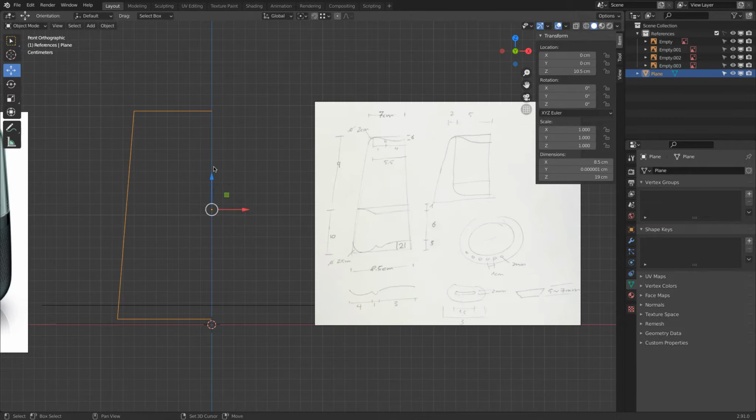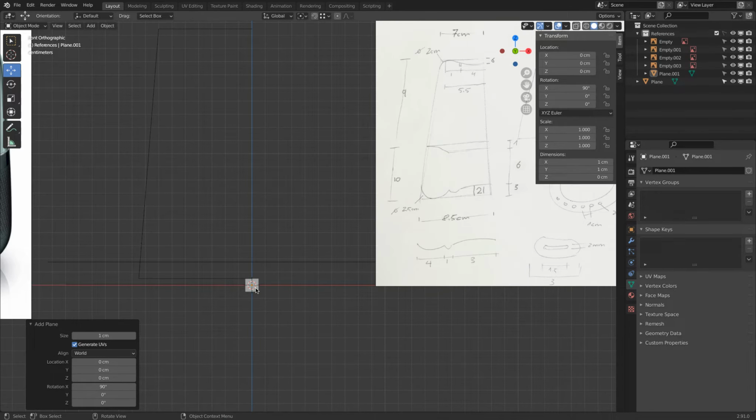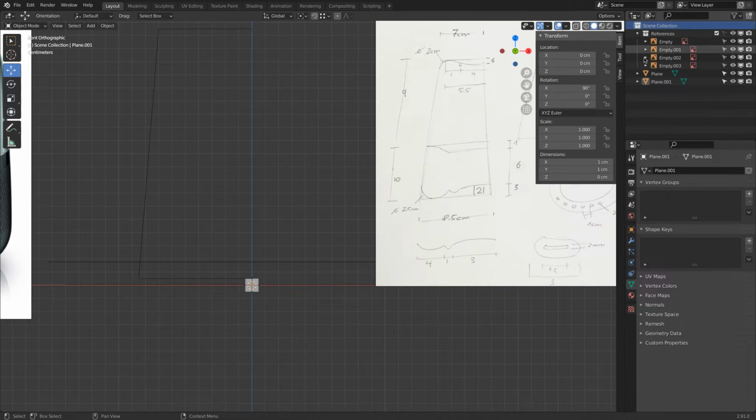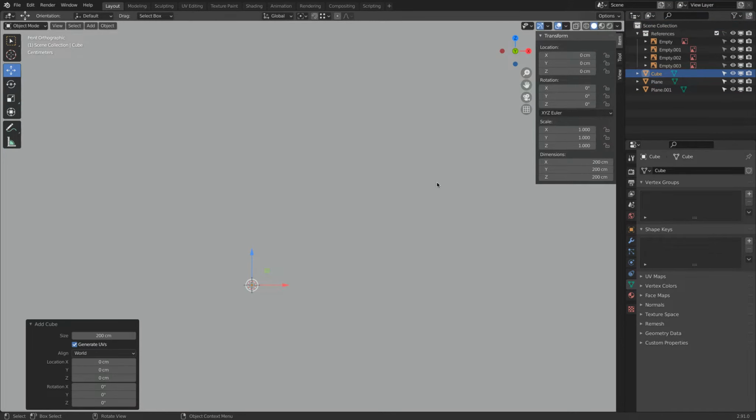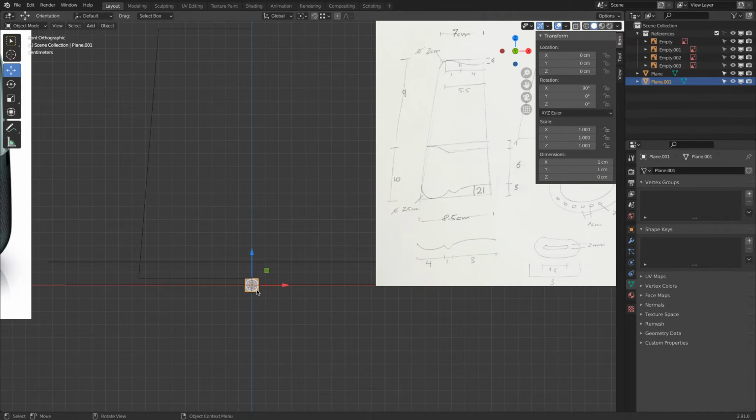So in this view, in object mode, Shift A, plane, and we will say size 1 centimeter and rotation 90. There is a little plane. Okay, so this one, I did the same. Hold on 1 second, let me do this one more time. Okay, good. Now it adds it to scene collection. After I talked about the reference collection being locked, I still had the reference collection selected again. So this one we bring up.